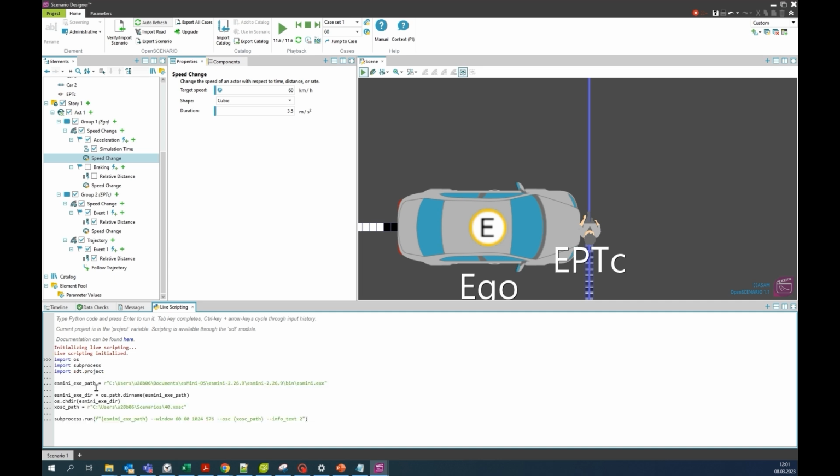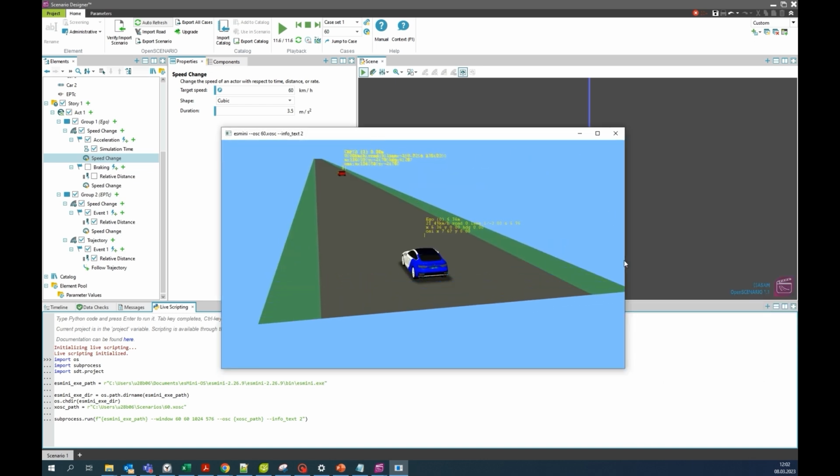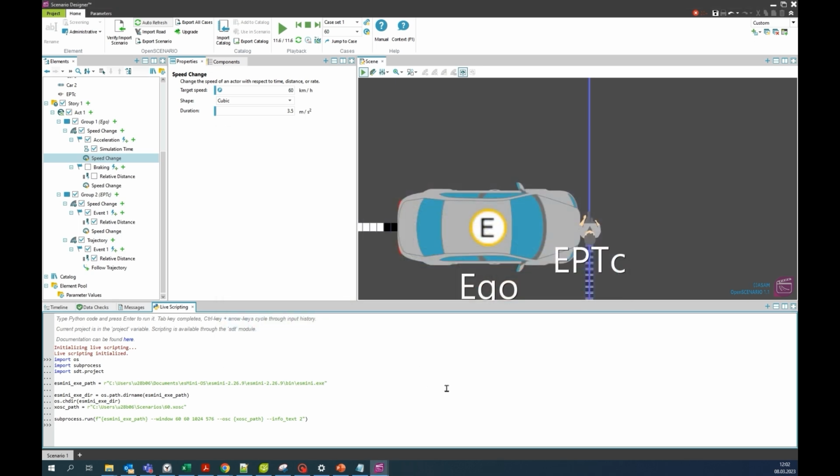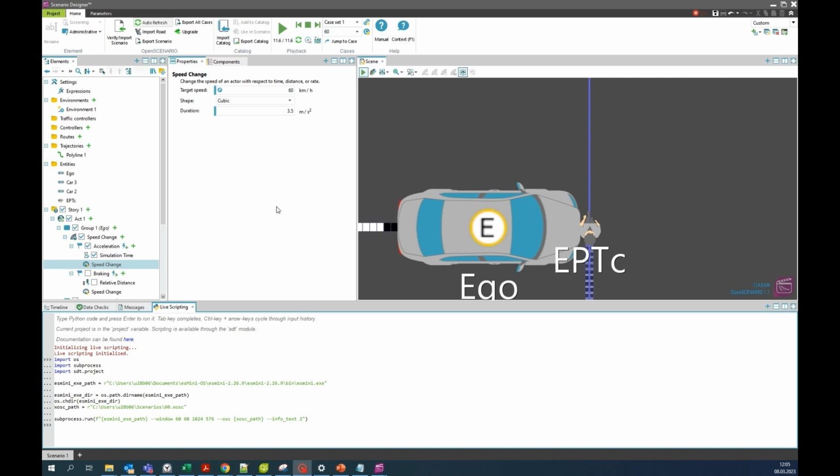And for that, we have our small script where it needs to be defined the ES Mini execution path, the OpenSCENARIO file that is going to be simulated, and with a simple run order here for example, the 40 case. Yeah, let's do the 60 case. We get an ES Mini replay of the action, so that it can be seen in a 3D environment. And when the collision happens, the simulation stops. And now the scenario is completed, and this has been done with the Excel calculations.